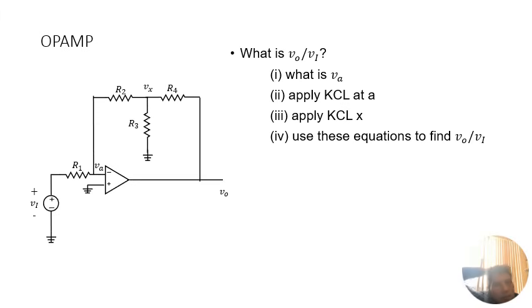All right, so here's kind of a more interesting circuit. As you can see, the underlying principle is always the same. If I know the voltage on one branch, I automatically know it on this branch, so it's going to be 0. So VA is actually 0 because the positive terminal is grounded. The next thing I'm going to do is assume that no current flows into the input terminals. That means it's easy to apply KCL at node A.